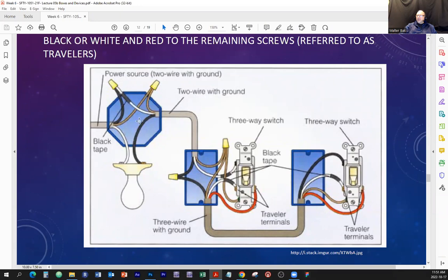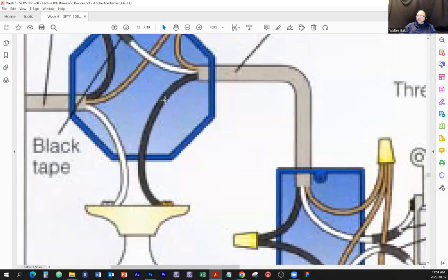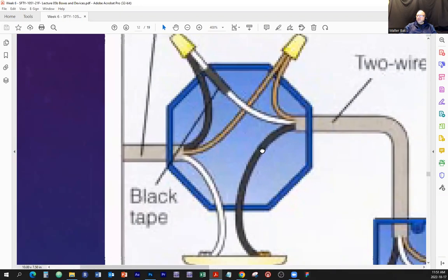Also, it's not a common practice now because you're going to have to supply the wires that contain the correct colors, but you will also see in some of the older installations. Look, this is neutral because it's white. Right? This is the neutral wire. This is the bare copper for the bonding.